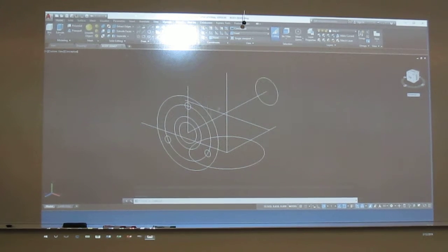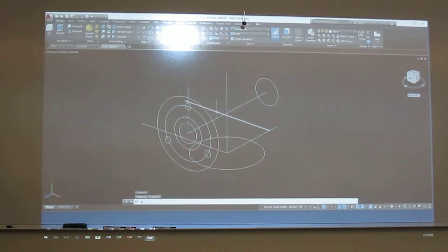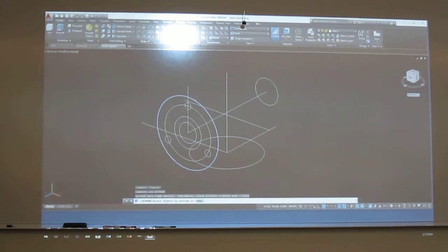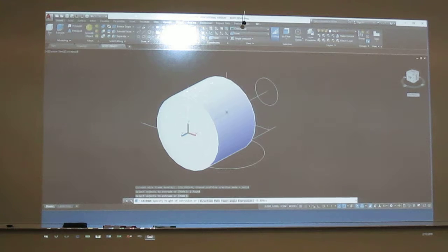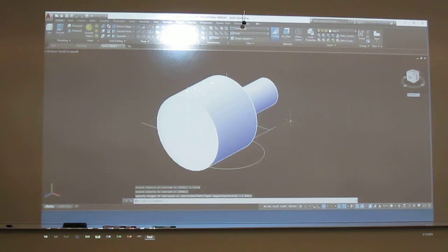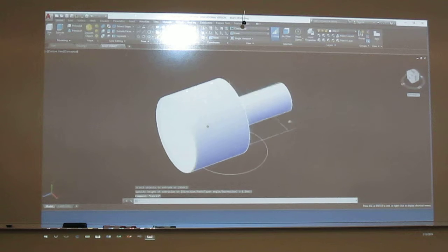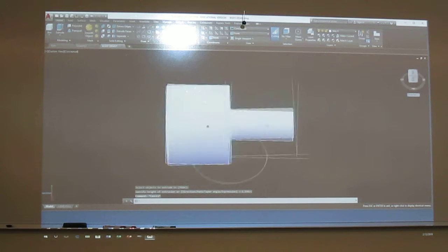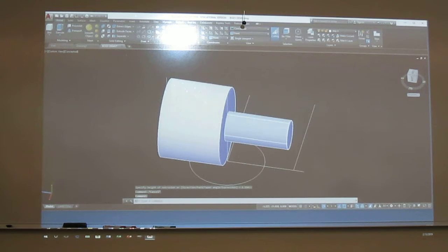They come into the object, but not all the way through. So I'm just going to do an extrude on this guy, and I'm just going to take it and snap to the middle here. Then I'm going to take this guy and extrude it, and do the same thing. I'll come back and snap on that middle. Okay? So I have just those two shapes thrown in. Now notice I didn't care where they went as long as they didn't go too far.